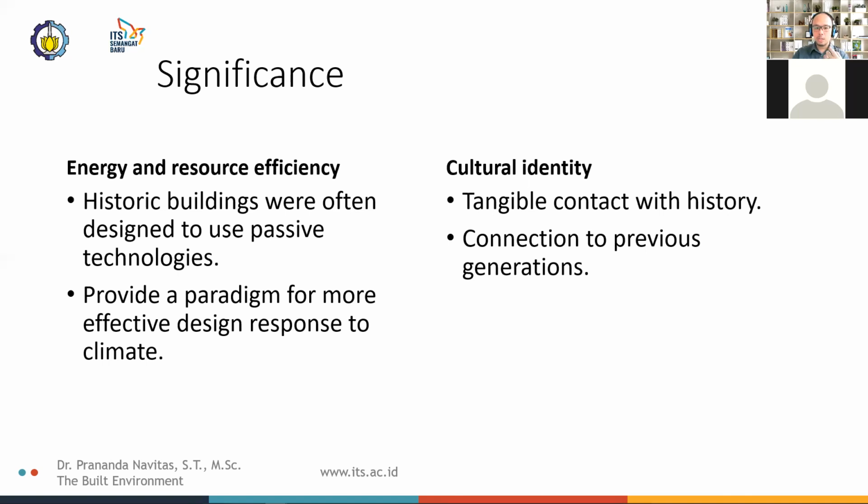Because mechanical support systems did not exist yet, historic buildings were frequently designed to use passive technologies that optimize access to daylight and conserve energy. Some old school buildings generally had rectangular footprints with their long axis running east and west. That affords generous access to high angle or indirect daylight and ventilation through operable windows on the north and south facing sides of the building.